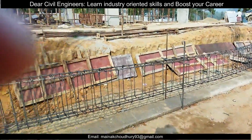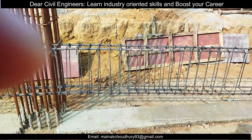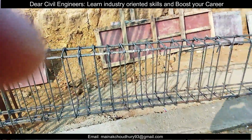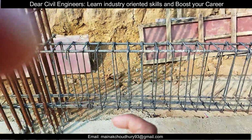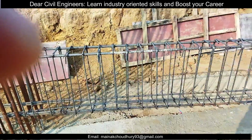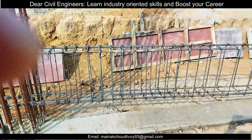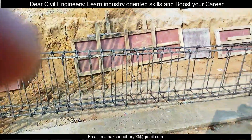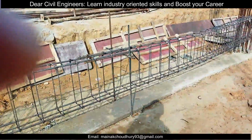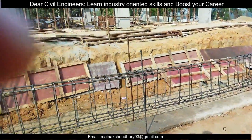So if this is L, leaving a distance of L/4 from the column or the support, then the lapping is provided. Either you can provide it at a distance of L/4 from the column, or you can provide it at the junction. There is a little bit of theory in that, but there are 2 locations. And at the top also you can see the location which is provided. The lapping is provided at the center, the central zone.